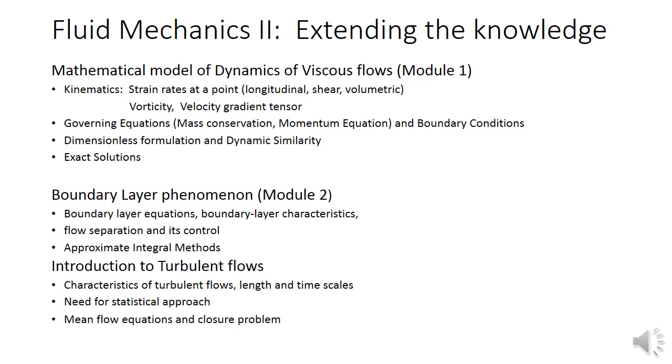And if you have a gas, which is also a fluid, then a gas obviously can have only two interfaces, either with a liquid or a solid, because there won't be any gas-gas interface. So interface conditions are there, which we will talk about in detail, and they play a role in constraining the fluid motions. In fact, if I were to tell you that the basic equations are the same for all fluid flows, yet when we look at different fluid flows, either in nature or in technological environments, they are all different. So what makes them different? These are precisely the boundary conditions that make the flows different from each other. So we will have a discussion on that.